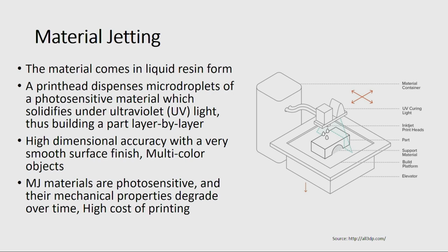The UV light is also attached to the head, then the layer will be cured, and then the 3D printing head will move over this, and again it will deposit material, deposit ink, and then it will be exposed to UV light and cured.